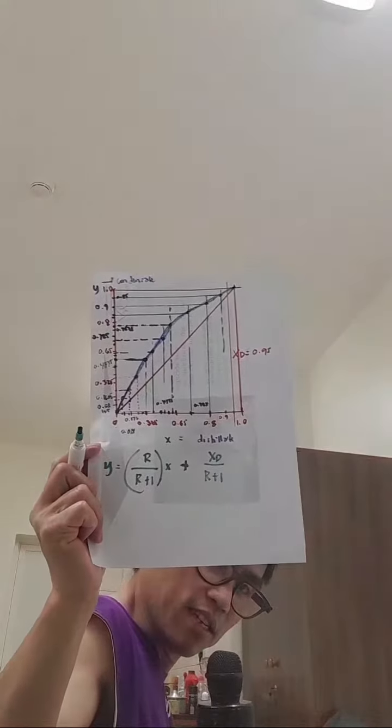See, you have to make your own analysis also. This is parallel, right? Because the slope and the y-intercept, or the b, are being added. So this is expected to be XD also. Got the point? Because this y here is solving for the rectifying line, or rectification, or upper operating line. And the upper operating line will be more on the distillate. So this is XD also, right? Correct me if I'm wrong, because the books I encountered never say that this is the mole fraction of the distillate. If you multiply that in the slope, it's just merely an x.